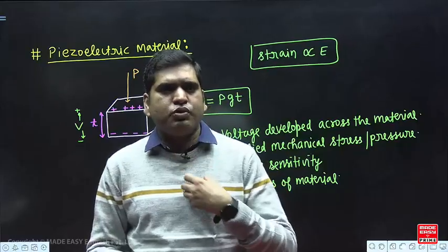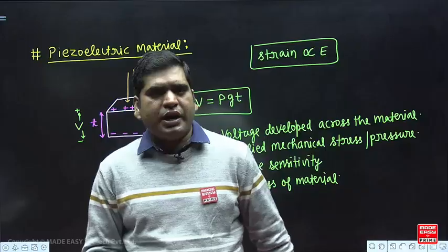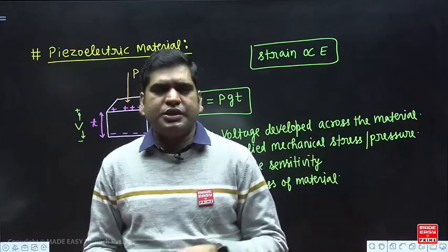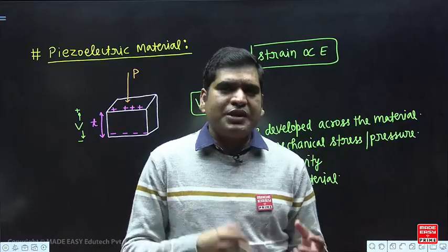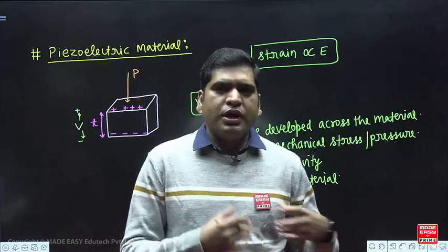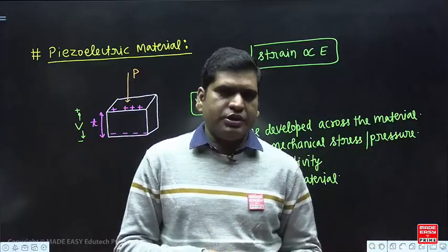Because of that pressure, some voltage is being developed and that voltage is leading to the current into the wire, and that current is getting amplified. So here the mechanical energy of sound wave is getting converted into the equivalent electric signal with the help of quartz. That is a piezoelectric material.